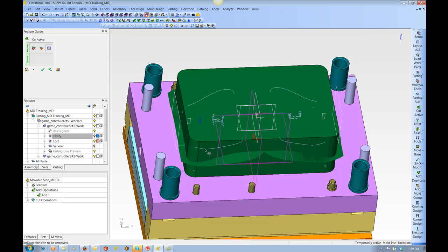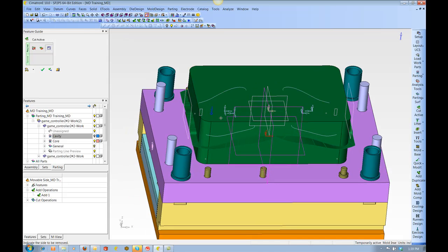And if it fails, it'll give you the option to simply push all that geometry into the insert file, and then you could manually fix the problem and do the cut inside the insert file. It's really not much more work to go about that way. Or you could go back and fix the problem and do this step again. If I hit this yellow X right here after it says it fails, then you just go out, fix the problem, try that step again.